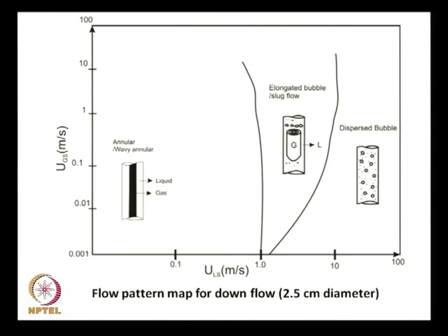There can be many more ways, but remember one thing, just learning flow patterns is not sufficient. You have to identify the flow patterns which operate under different conditions, and you also have to know the range of existence of the different patterns. The graphical way is definitely one. There are other ways also. One particular way is to actually model the transitions and develop mathematical equations to predict the transitions.